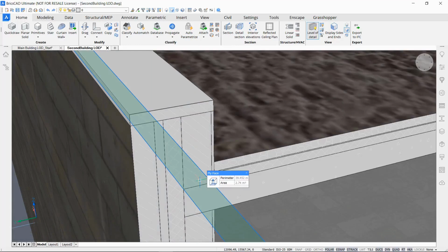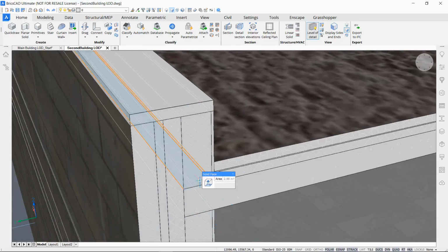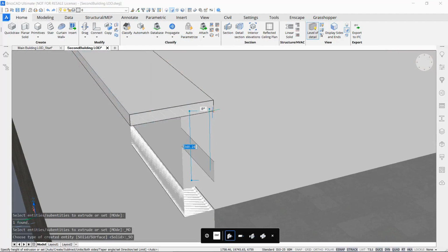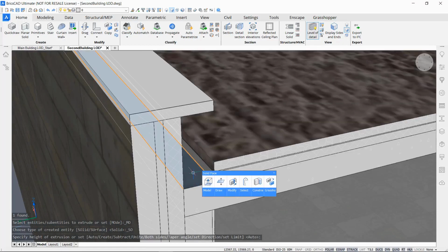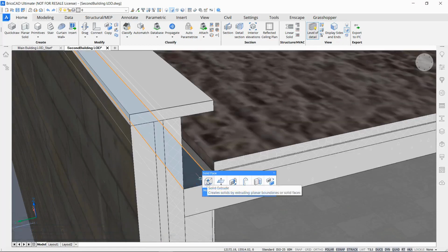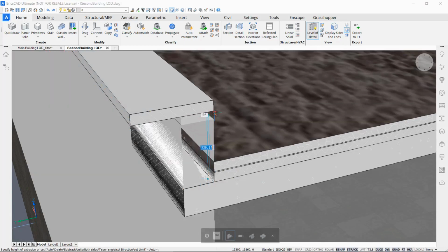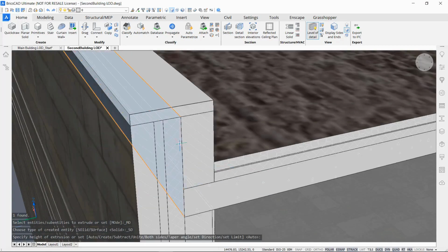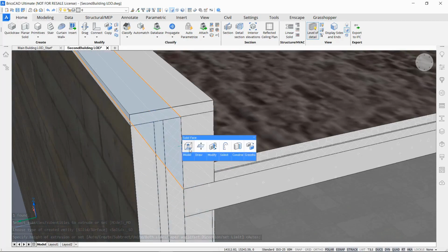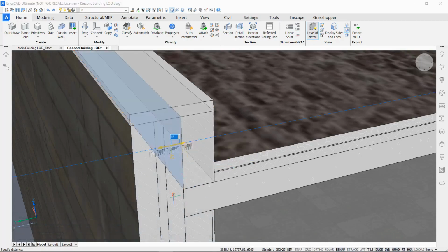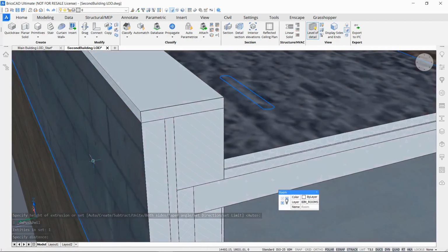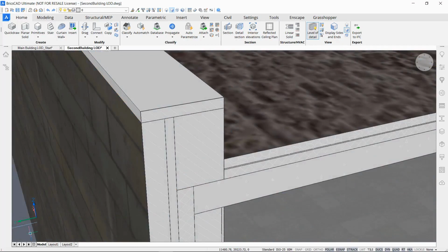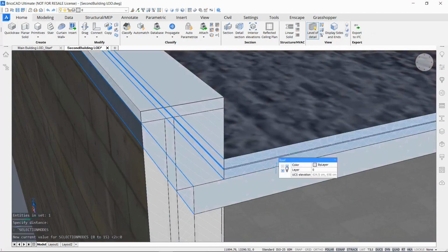as well as here underneath, click on tab once to have the solid face to delete the whole part of this one like this, and then again to use the same surface, and instead of deleting, we're going to add in a new solid like this. Afterwards, I'm going to make this solid a little bit bigger on the side, push pull it for the next solid, next surface, and my new detail should look something like this. Let me disable the face selection.